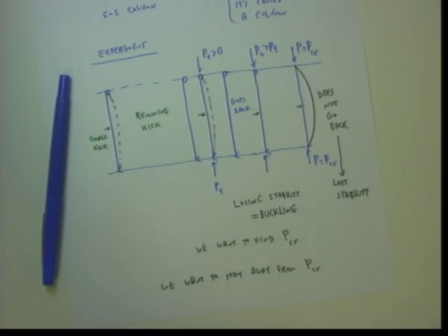Yes, sir. Does not go back means he stays there. I mean, you gave a kick, it gets bent, and it does not go back. When you remove the kick, it did not go back. You gave a kick like this, and it bent, but then I removed it, it comes back. It comes back for various P's, but when P equals P critical, it does not come back. So then it loses the property of being restored.